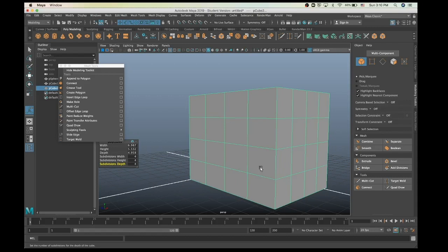So you added subdivision from the beginning in your model, but sometimes you don't add more subdivisions, and later in the process of your modeling you need to have more loops or edges. This is a tool, insert edge loop. This is a tool that helps you to add more edges or basically subdivisions to your model.